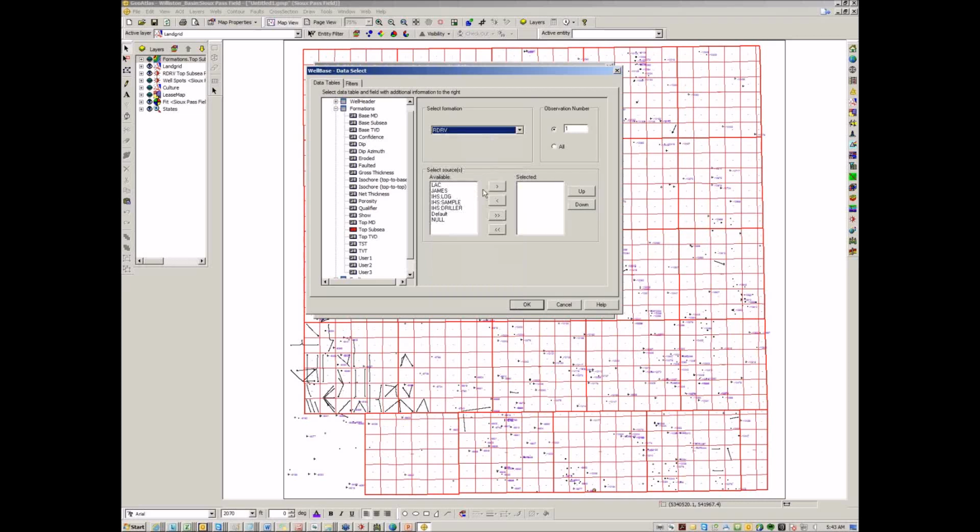Okay, I have a number of sources available. In GeoGraphics, you can flag each pick with the source of the data so you can decide which sources are more or less reliable. I'll pick my own source. Of course, I like my picks. I've done a good job here. My colleague James is also correlating in the Red River, so I'll pick his picks secondarily. If I have a pick, I'll get it first. If not, I'll take James. And then if neither James nor I have looked at a well, I have a variety of vendor sources from IHS that I'll pick as my other choices.